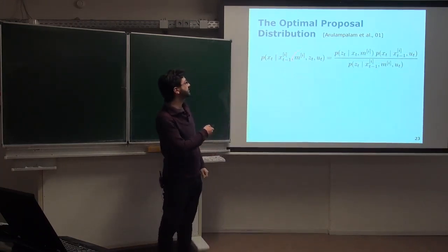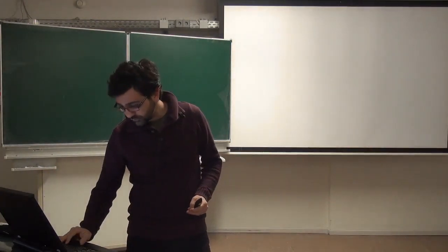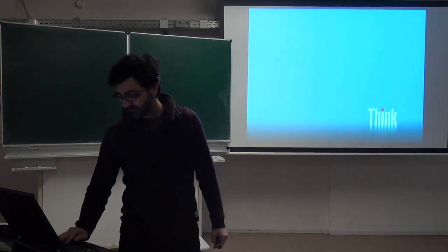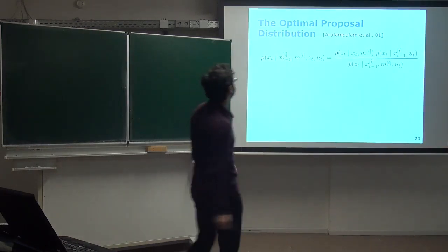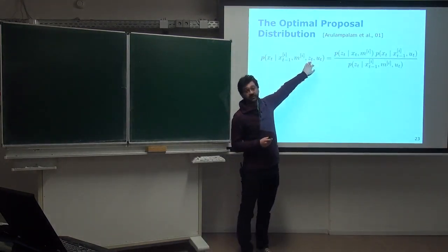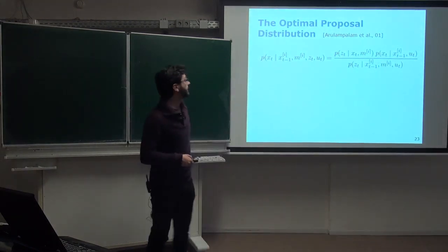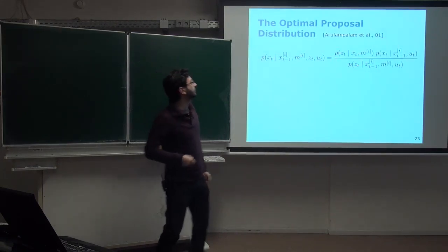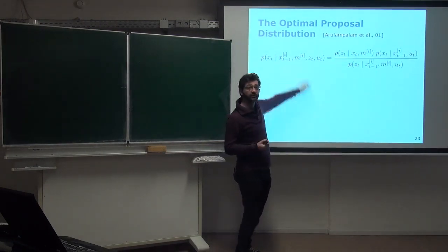So we can sample from the distribution that takes the previous trajectory, the map that we computed so far, and also considers the last measurement from the laser and the last measurement from the odometry. Okay, so we can see this one as this product. This is similar to what we have done when we were discussing the Bayes filter for this problem here.